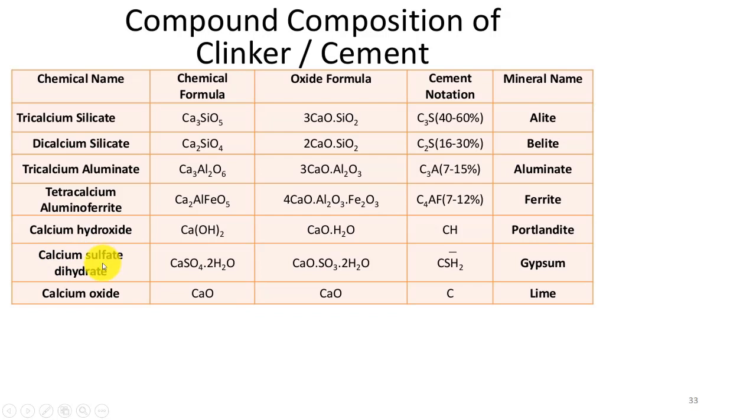Second last, you have calcium sulfate dihydrate, which is gypsum. Basically gypsum is added to delay your setting time. Lastly, you have lime, quicklime, which basically contributes toward the hydration reaction.